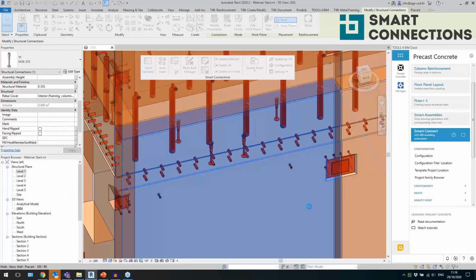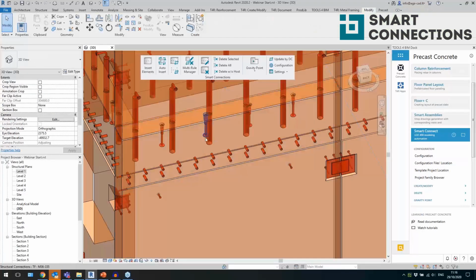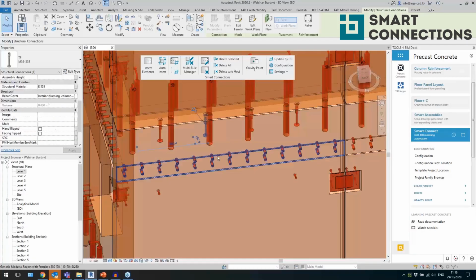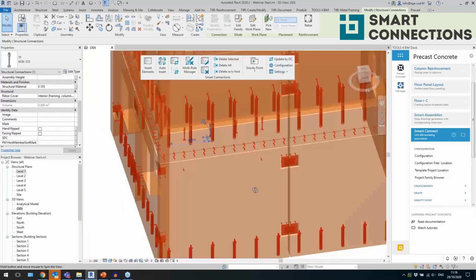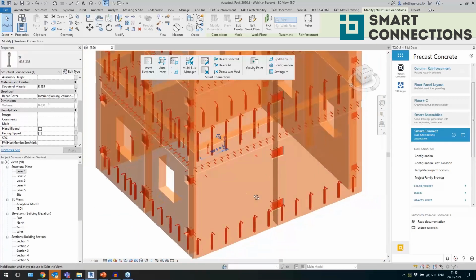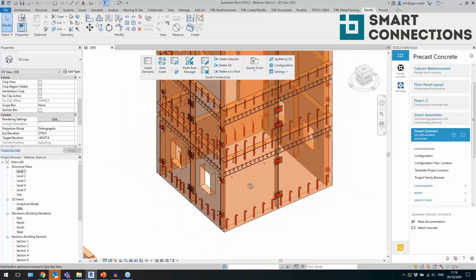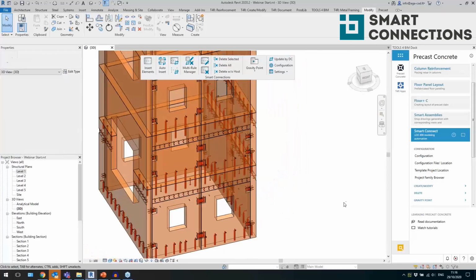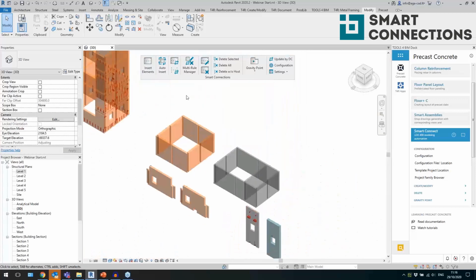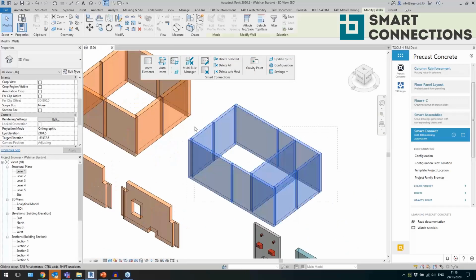Let's see if it will be better. Right, so you can insert them like this or adjust the position manually as well, right? It depends on how complex your walls are, but now you can make individual changes for any element. And as I said, this depends on what kind of families you use.